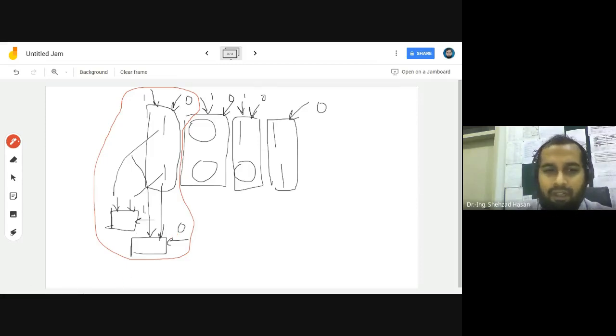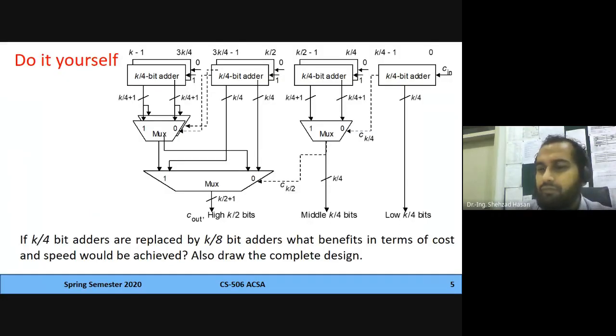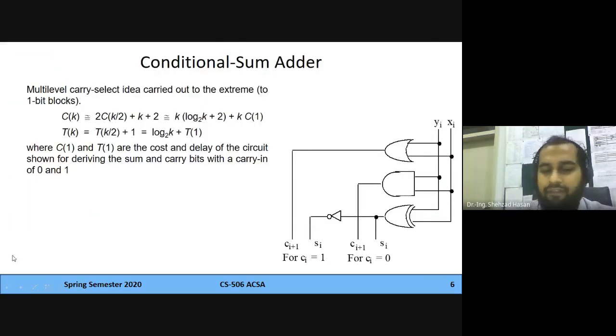Now the only difference in that case is that instead of designing it as a ripple carry adder, we have a different circuit for that. So this is the circuit. Instead of a ripple carry adder, we have the inputs over here. We have an OR gate and an AND gate, an XOR gate, and an inverter. So it's a simple circuit. Both the bits are going to come over here, and you're ORing them, you're ANDing them, and you're XORing them as well, and you're getting these four results, right?